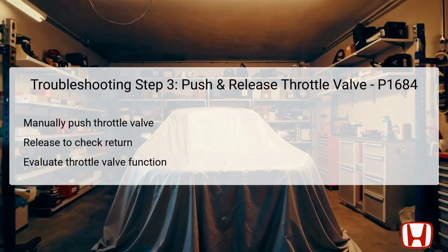In this step, the technician should manually engage the throttle valve by pushing it open to check its mechanical response. Following this action, it is vital to release the valve and allow it to return to its default or closed position. Observing this return is critical.